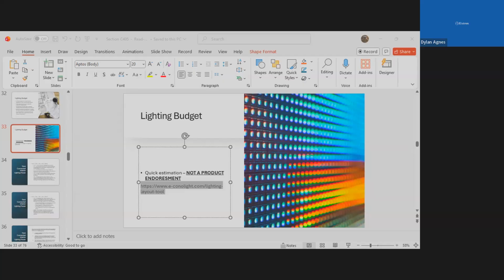Then you can change the room size, length, and width. You can change the luminaire, go in and edit it, change the projection factor, details about the luminaire, as well as its actual shape. So if you want to jerry-rig your own custom one that you're thinking about using, you can. You can also set room size, reflectance, work plane height, ceiling, walls, and floors, and specify the foot-candle you're looking for versus calculated luminaires and power density. This is a great tool I've been using since grad school, but a lot of the lighting manufacturers have one. I just, out of habit, go back to this.